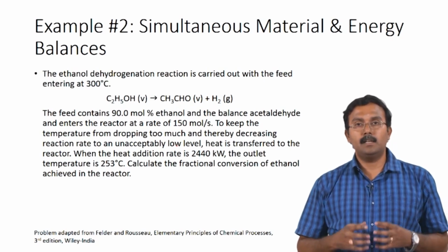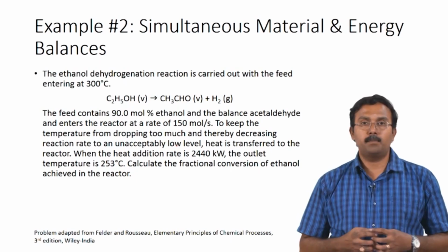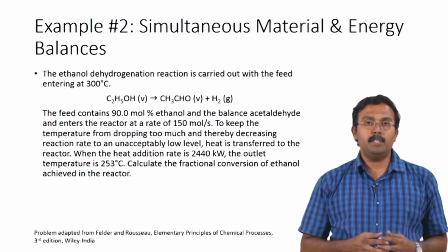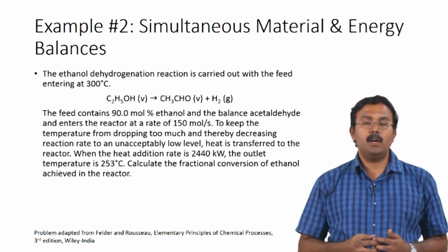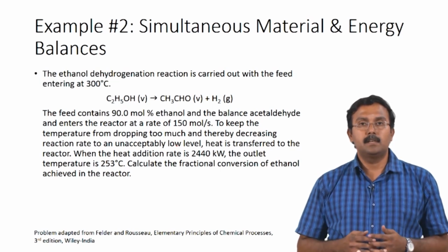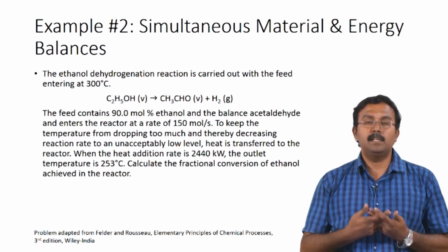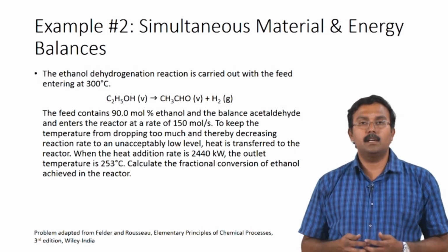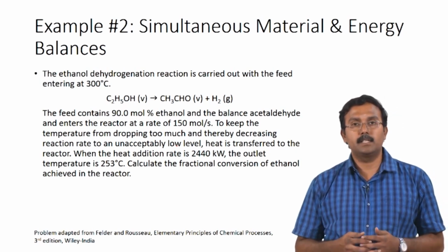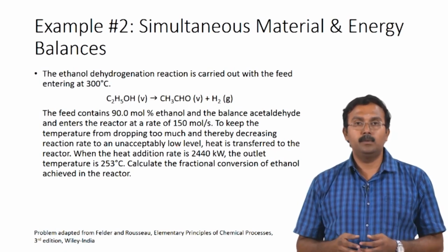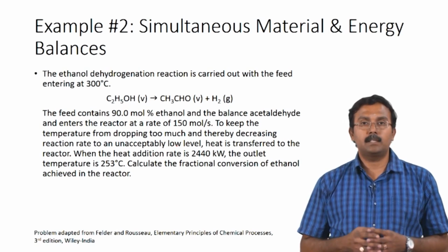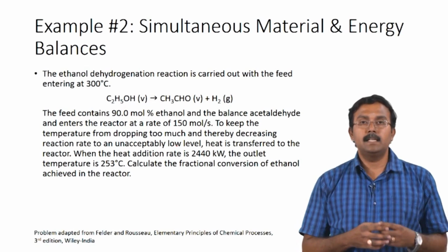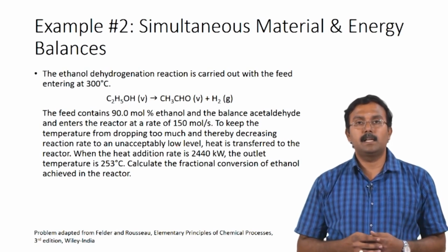If you were to look at this problem and compare it with the previous problem which we solved, in the previous problem we were given the conversion, however, we were not given the exit temperature. Here we have actually been given the exit temperature, but not the conversion. We have been asked to calculate the conversion. So, we can actually do this. We are trying to get this value. For this, we will try to perform the energy balance and the material balance simultaneously.